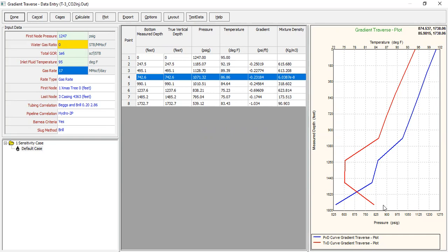yeah, I will do some scenarios. I want to check at what maximum temperature we can maintain dense phase CO2, or what is the minimum injection pressure at the wellhead to achieve dense phase CO2, or what is the maximum rate to maintain or to achieve the dense phase CO2. Okay, so those are the scenarios, the exercise that I'm going to do.